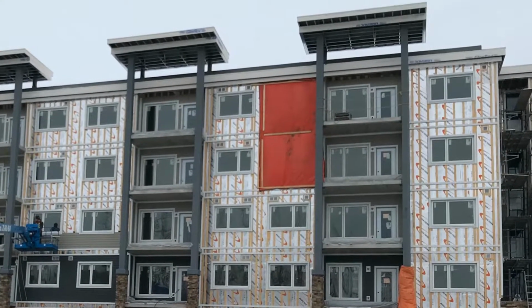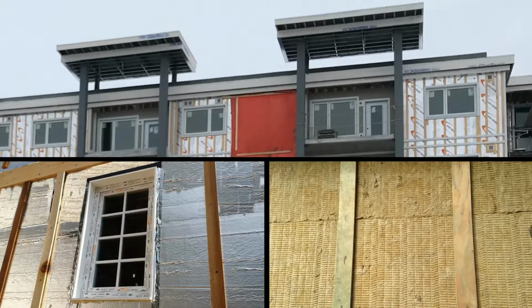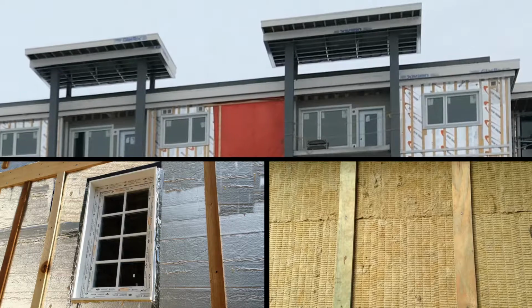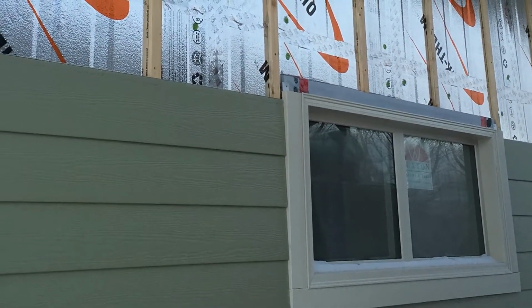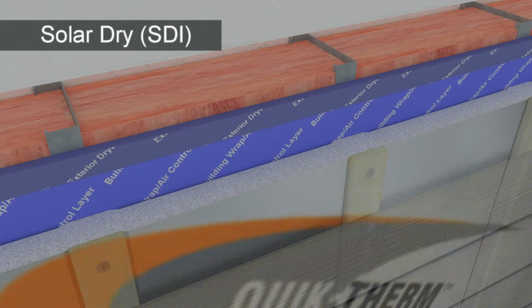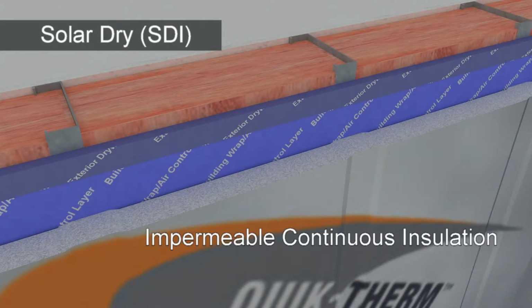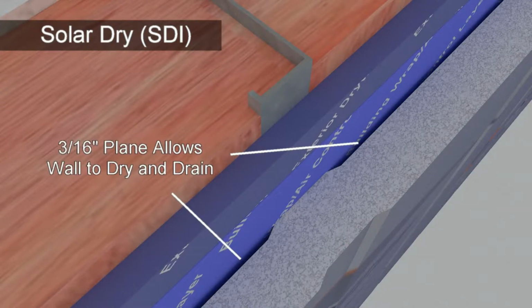Quik-Therm insulation has considered the challenges and benefits offered by both rigid, flat foam board and permeable mineral wool insulation products, and has engineered a third solution to achieving exterior continuous insulation without trapping or absorbing moisture. Quik-Therm Solar Dry offers the benefits of an impermeable continuous insulation board style system with an inherent drying plane that allows the wall cavity to breathe, dry, and drain.